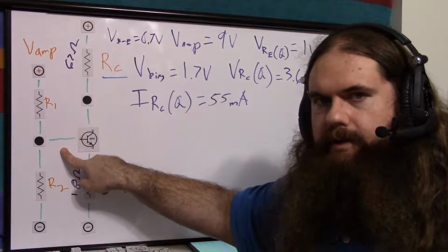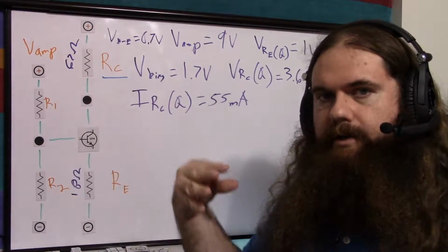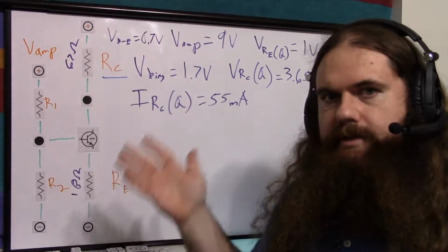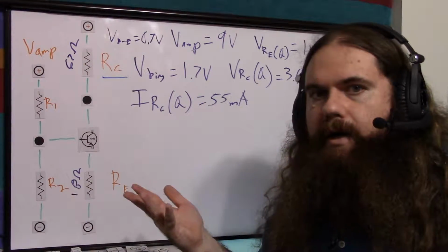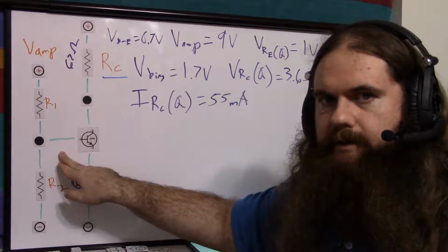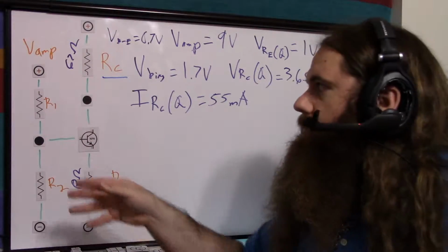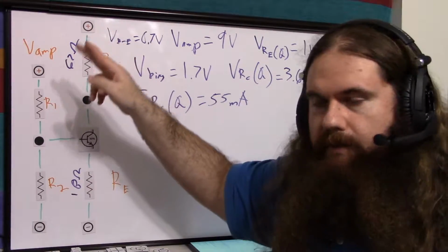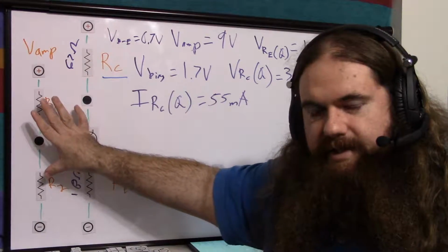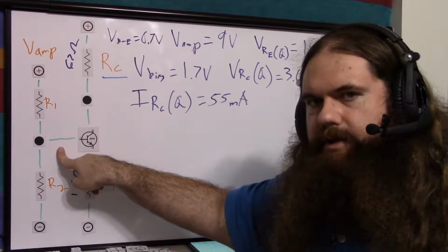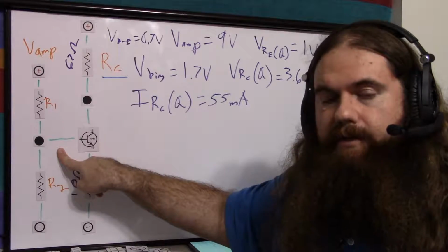You have your base current, right? Multiply that by 10. There's the current you need. Then the total resistance, right? So you have R and you have I. You have 10 times your base current. You have your V, your amplifier voltage from here to here, because it's in series, so they add together. V equals I times R. So R equals V divided by I.